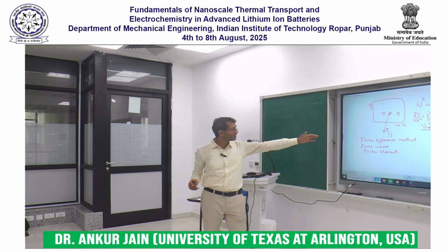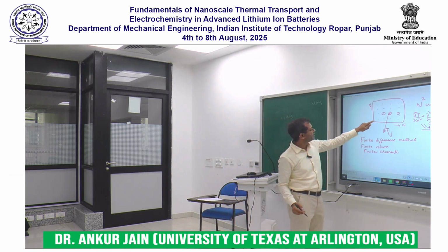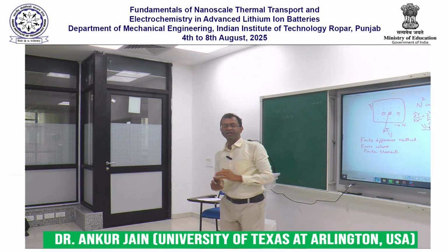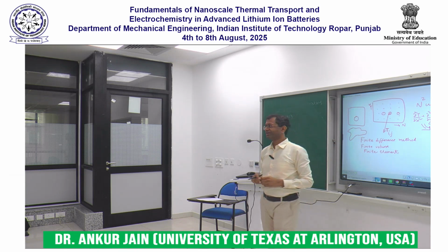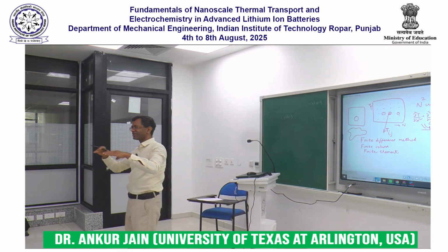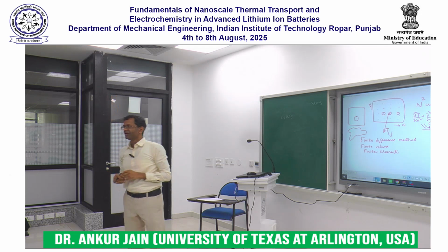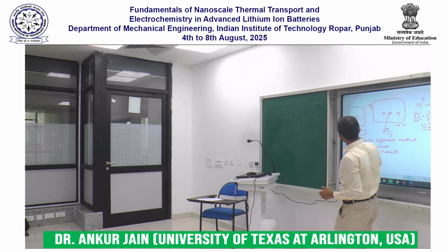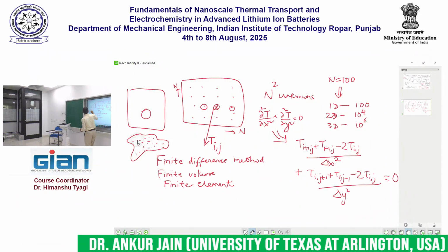As I said, finite difference is the simplest, but it has its own limitations. For example, here I need my nodes to be defined along the x and y directions, right? What if my geometry has a hole in it? Or what if I have a really weird irregular geometry? Then I will not be able to define my nodes in a regular orthogonal fashion, right? It is important in that case for us to be able to solve problems where the nodes are located arbitrarily. The nodes could be located wherever you want, and you want to solve the problem there.